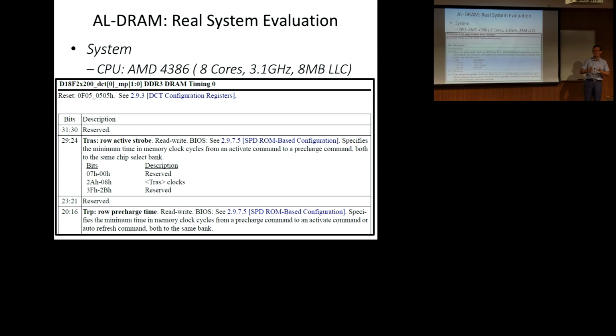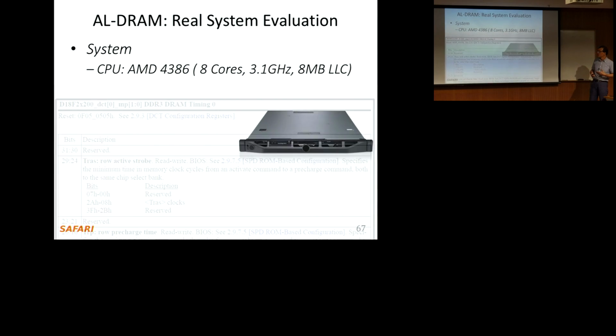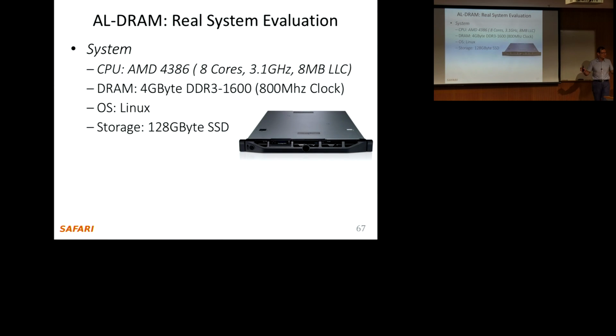And sometimes they get errors. Okay, they're annoyed at that point, and then they back off. So it's like having an ECC at the human level, right? You're the error correcting logic, and you back off a little bit after that. The problem is you cannot dynamically do this, at least in this system that we have. So we had to do it statically, and we basically wanted to ensure that the system is operating lower than 55 degrees Celsius. We didn't ensure that, but the system operated lower than 55 degrees Celsius without us doing anything.